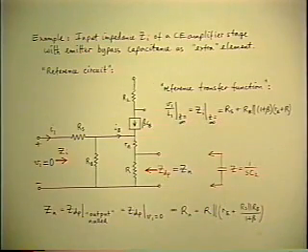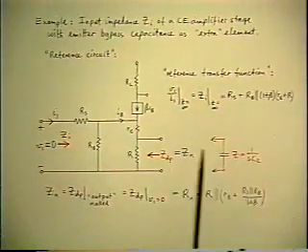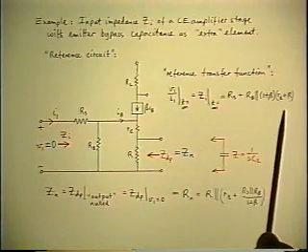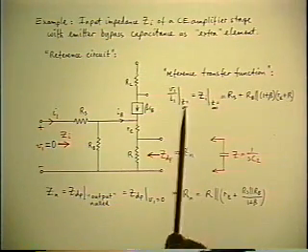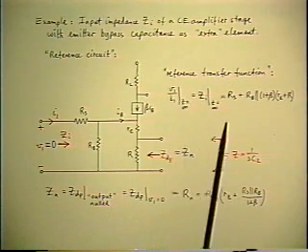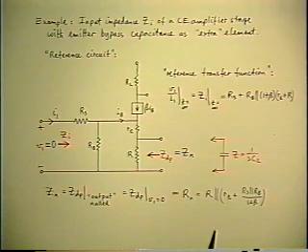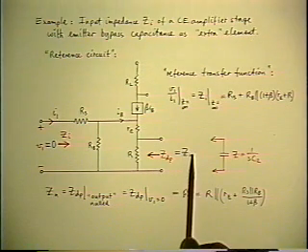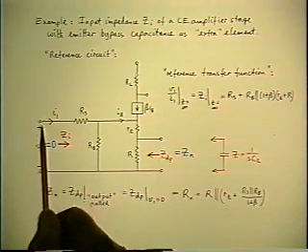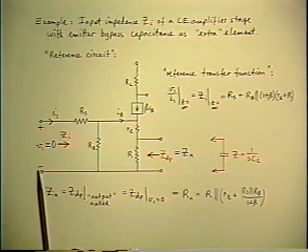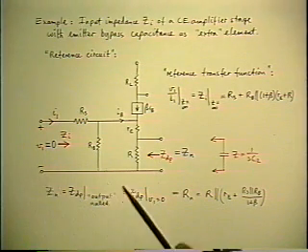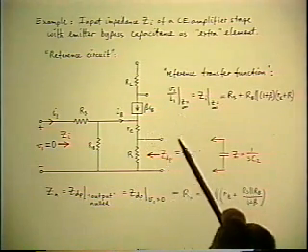Okay, the modification is that in the special case where the transfer function that you're correcting with the theorem is a self-impedance, which is this case, the null double injection calculation gives an answer that can equally well be calculated by simply saying that you look in from the second source with the input shorted, forgetting about the argument to do with the adjustment of the null.